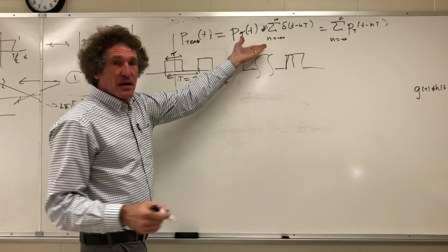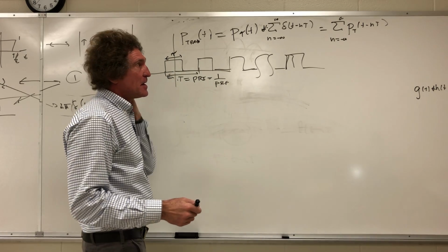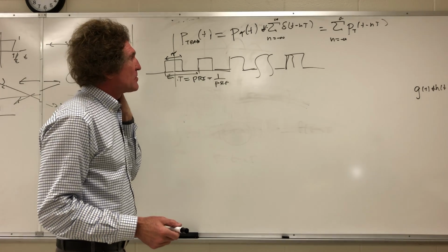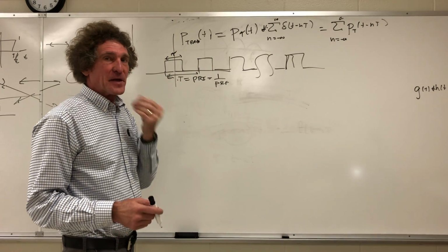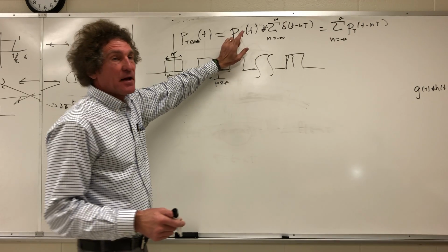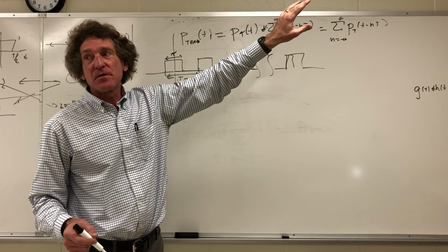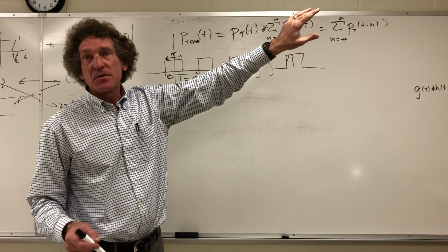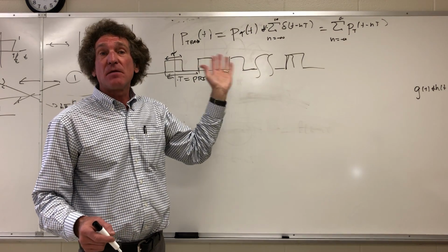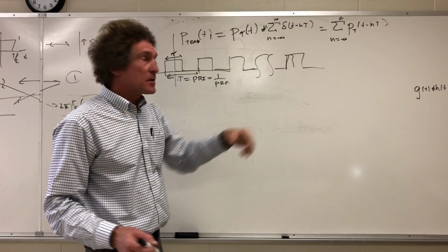All right? Now, when you have that there, we have to see what it looks like in the frequency domain. So, there's a lot of bright people in here. How would you go ahead and take a look at what this thing looks like in the frequency domain? Anybody? Start there. What happens if I have h of t convolved with x of t? What's the best way to take a look at what it looks like in the frequency domain? Take the transform of x of t, it would become X of omega. Instead of convolution, multiplied by the transform of h of t, which would become H of omega, right? So we're going to do just that.